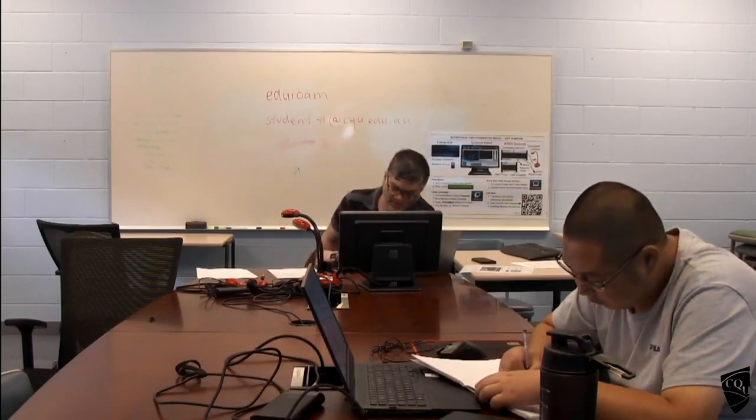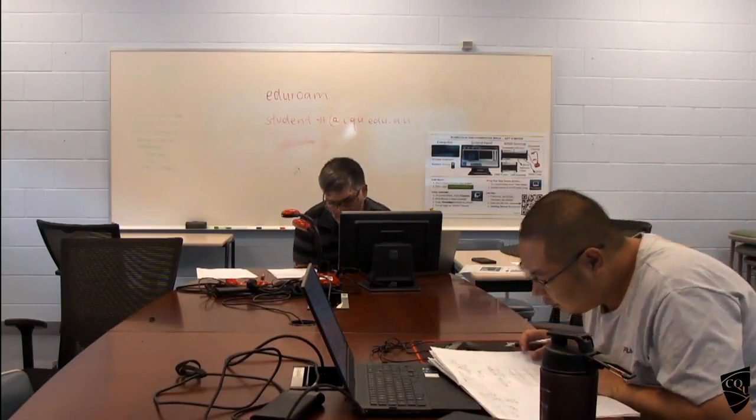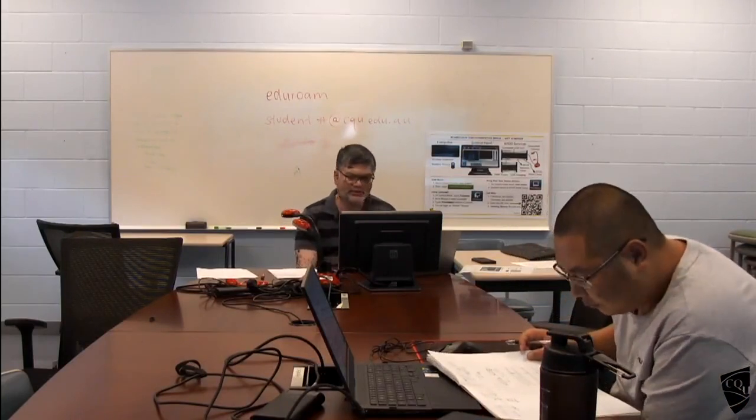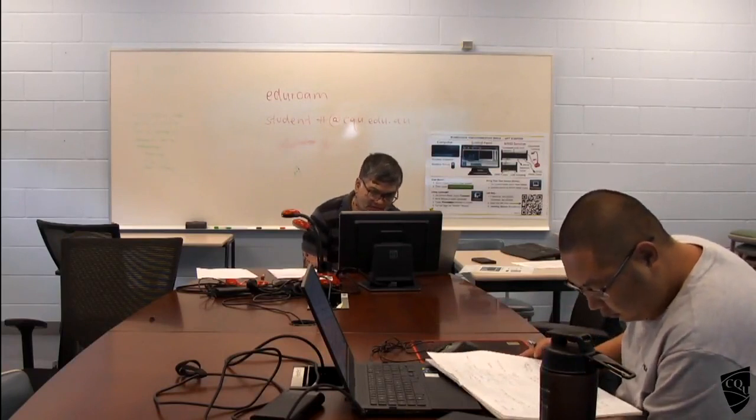Remember, x and y are the shorter and longer spans, not the coordinate system. It is not according to the coordinate system. Whichever effective span is shorter, that is called Lx. Whichever effective span is longer, that is called Ly. That is important, because in the exam, in the class test, some students use Lx and Ly as they like.